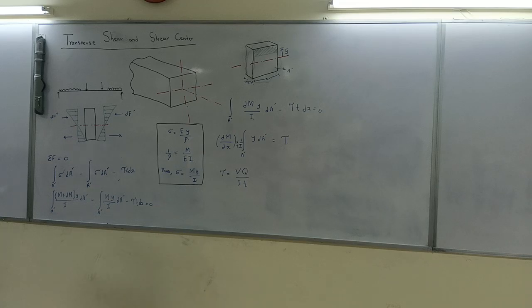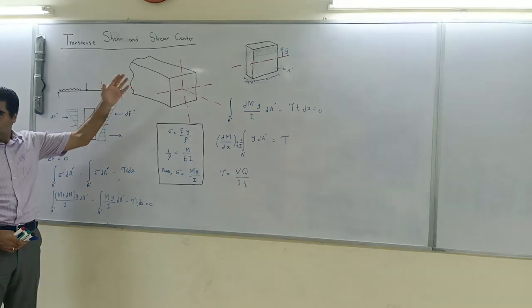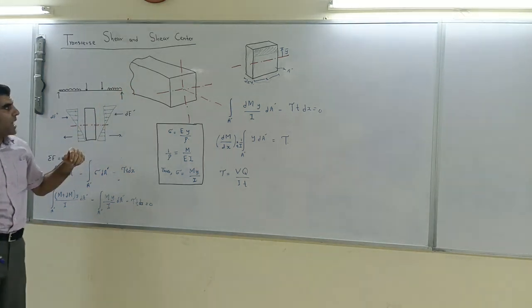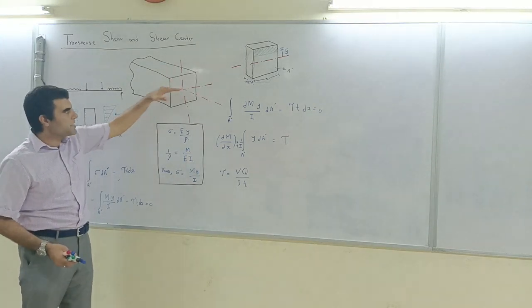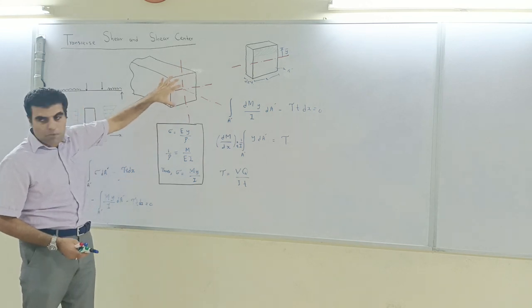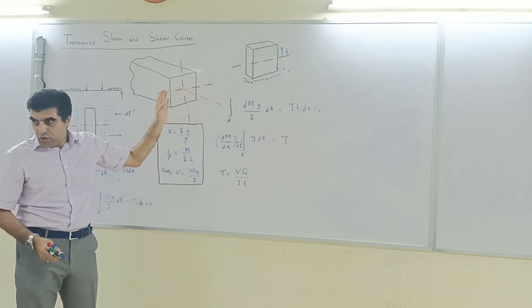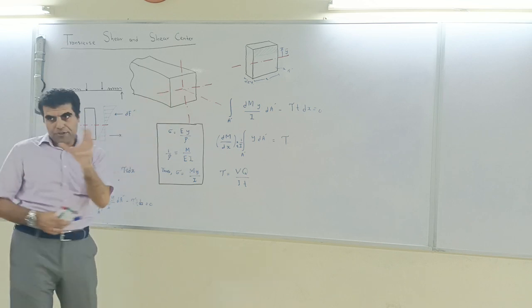So one of the issues which we normally encounter is not having the load applied exactly at a point which would avoid twisting. And we had a very detailed discussion on how we can apply the load in such a way that twisting is avoided. So for example, if we have these axes, what are we saying? We imagine this is a random cross section and we apply the load. Which axis is best for the load in order to avoid twisting of the cross section?